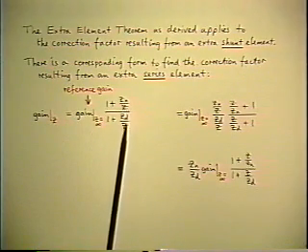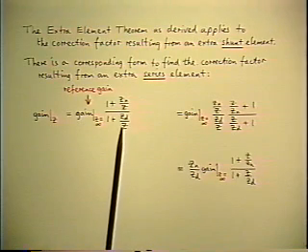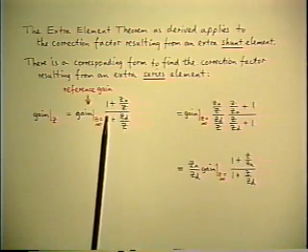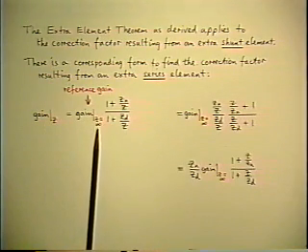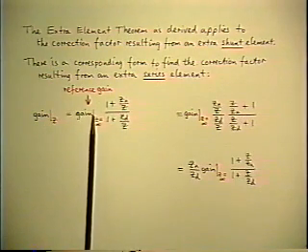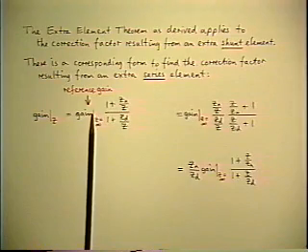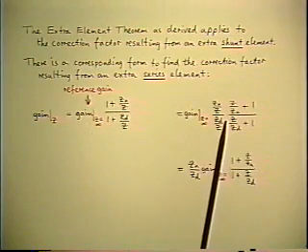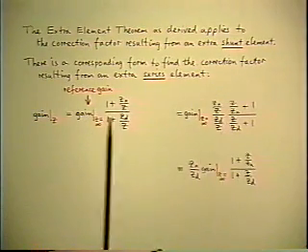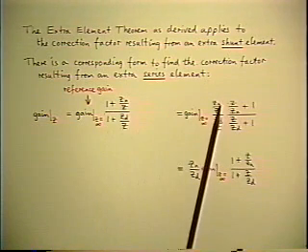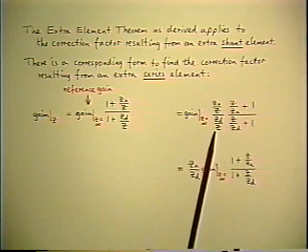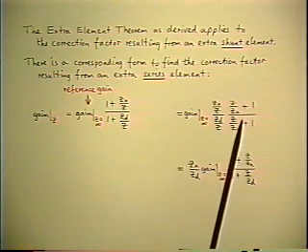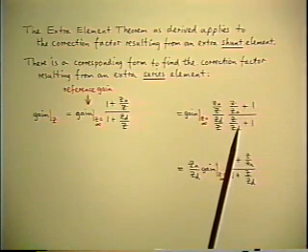Notice that if you let Z go to infinity, the correction factor goes to 1, and of course the gain goes to the gain when Z is infinite. That's essentially the definition of the coefficient. We can do a little algebraic manipulation and bring out Zn over Z from the numerator, Zd over Z from the denominator, which has the effect of inverting the ratios in the correction factor.